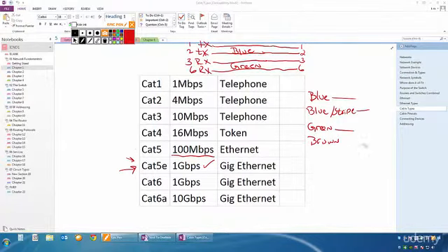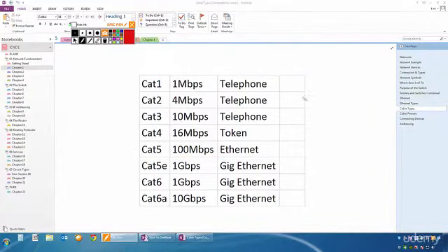These are not going to be your transmit, and these are going to be your receive. You want your color pairs to be a pair, which means if you're going to be transmitting, you're going to want to be transmitting on a pair that has a certain amount of twists per inch. You don't want to have a pair of receiving or transmitting wire where one of those wires is green and one of them is a total different pair sitting somewhere else. So I want you to think about this. This is what I used to do. I used to do my colors in order. And let's actually get to our cable pinouts anyway, since that's where we're kind of going to.